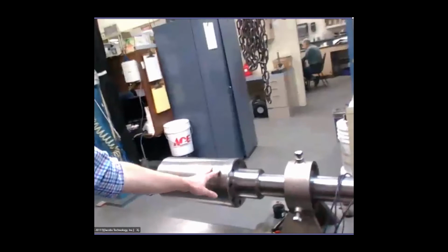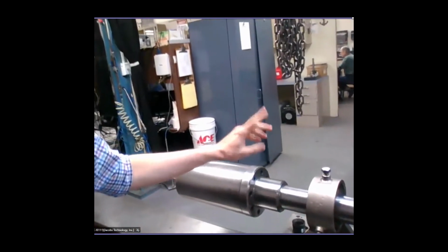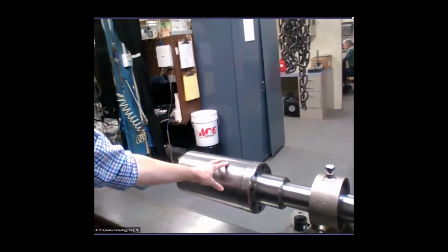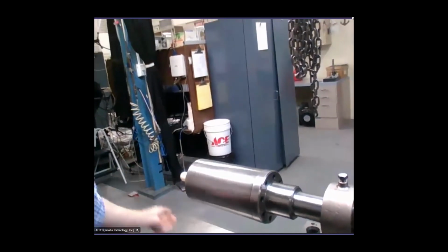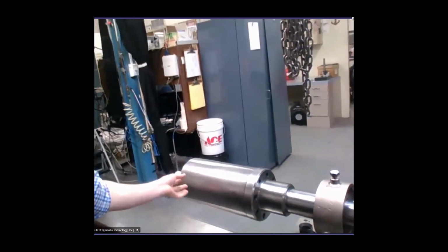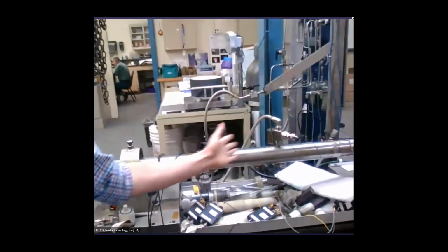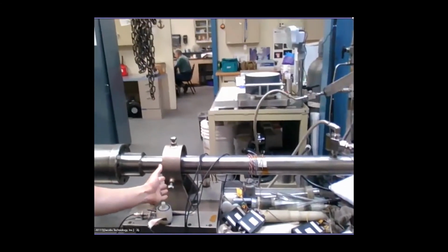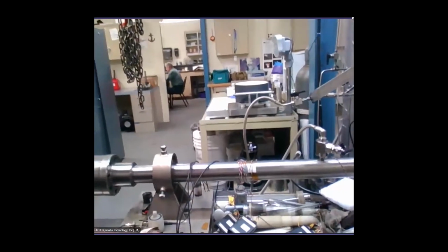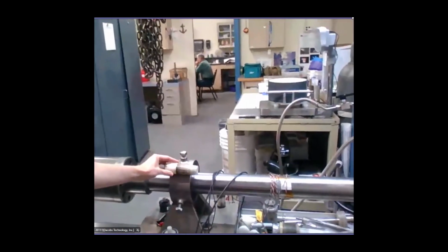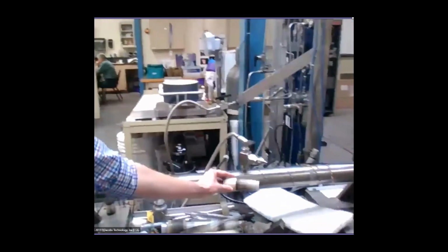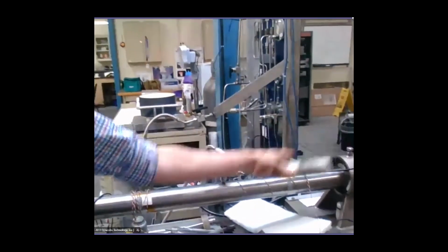So we're down here at the business end. Here's our breech. It's identical to that of the flat plate. So this is where we put in the gunpowder. This is where we would put in the signal and the electric primer to fire the gunpowder. Now in the flat plate, this would be our barrel. But as we said, this is filled with hydrogen, pressurized hydrogen. And we have a Teflon piston that's sitting down here at the end that then starts accelerating and pressurizing this